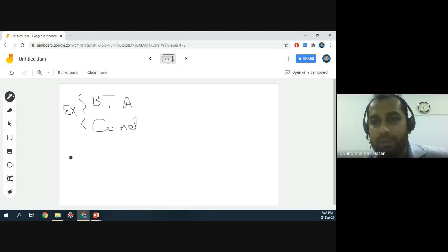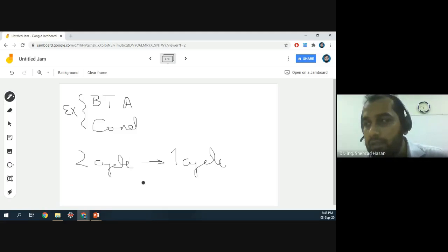That's even more than the load-use hazard, because in a load-use hazard we had just a single-cycle stall, but here we incur two-cycle stalls if the branch is taken. Now this can be resolved, and instead of two cycles, we can have just a single-cycle stall if we do these two things earlier in time. So we can save one cycle for every taken branch instruction if we calculate these two things earlier in time.